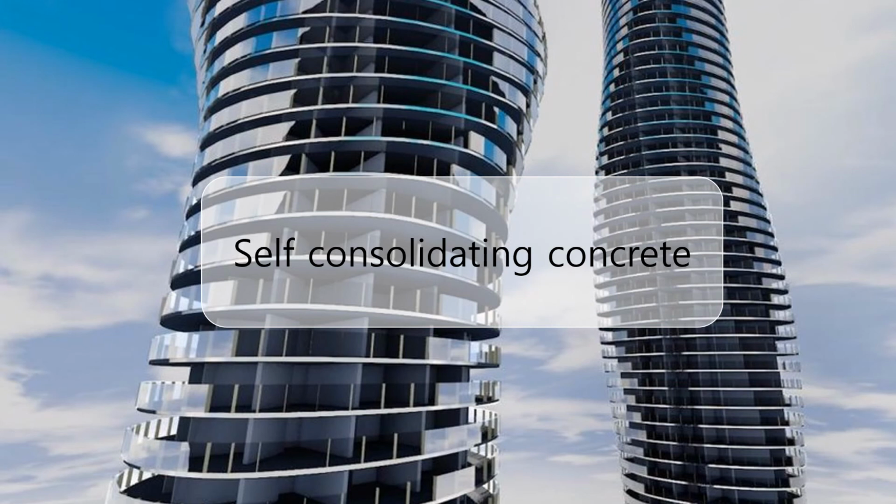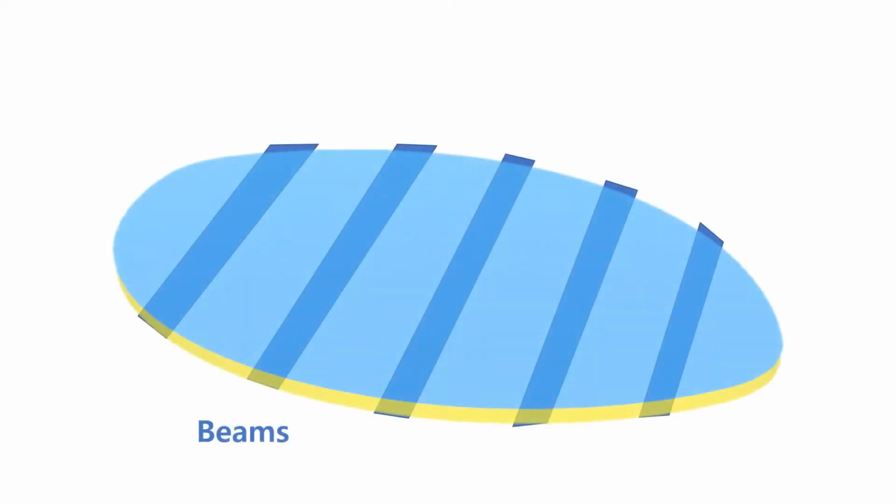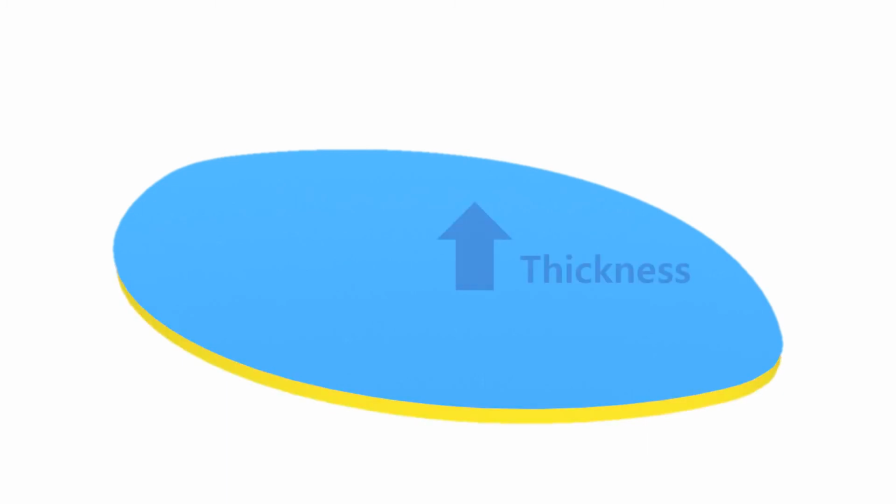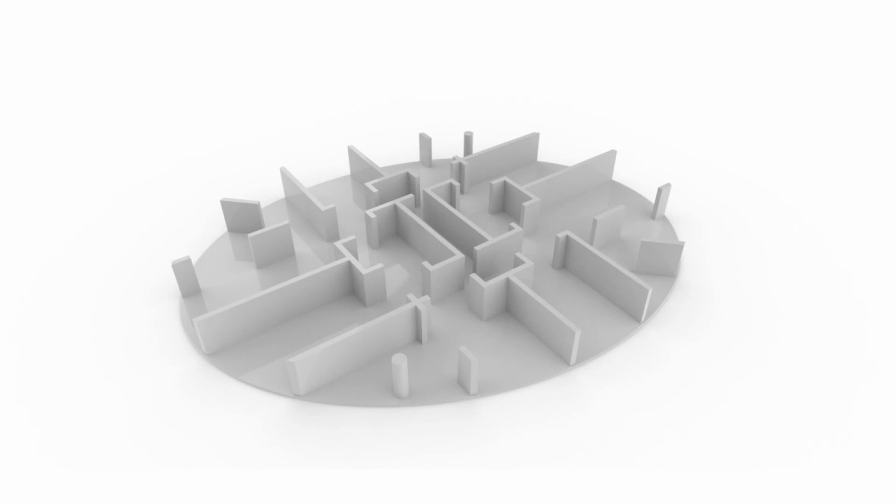There is another method to sustain structural stability from collapse generated by unique design. It is self-consolidating concrete. General building has a beam to support the slab load. But if the structure is designed without beams, the slab should have high volume and thickness. And also, it needs finer concrete specification, called for 70 megapascal columns, walls, and beams, and 50 megapascal slabs.